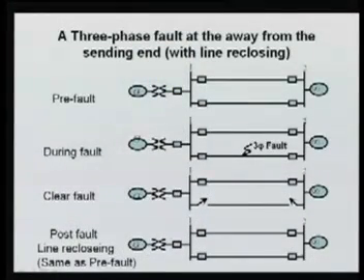So once any live animal or bird on that phase dies, all these three phases are operating in isolation. So the fault is automatically cleared after one shot. The circuit breaker for an EHV transmission line normally has some reclosing facility, so with that we can see the line reclosing as well.